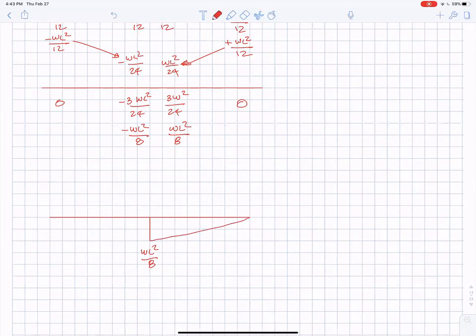And I knew I wasn't going to get the maximum moment, but the moment in the middle of the spans was going to be close. And by similar triangles, I knew that was going to be WL squared over 16. And then I knew, we talked about this total static moment. You add WL squared over 8 to that.